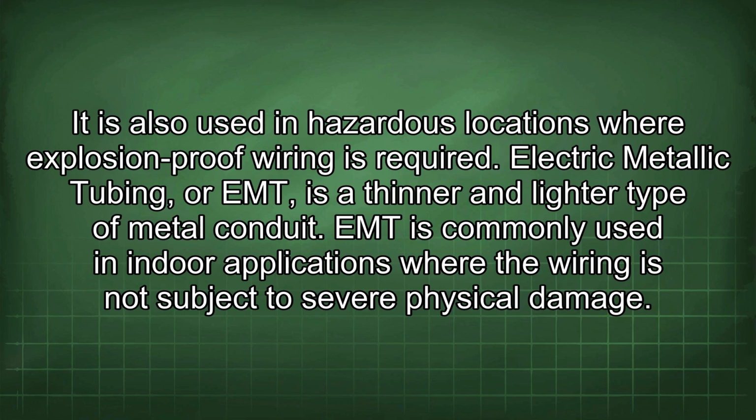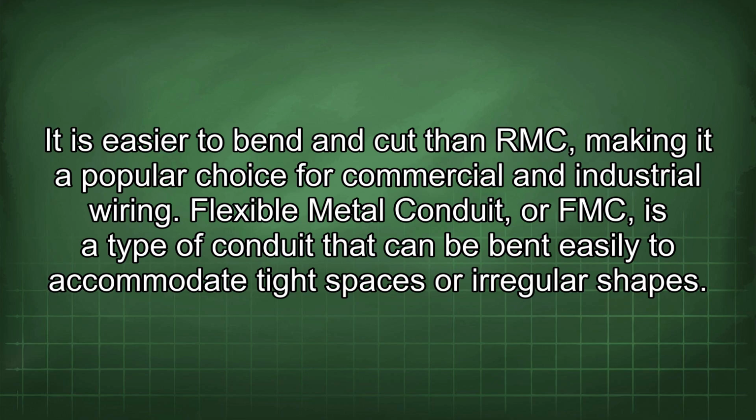Electric metallic tubing, or EMT, is a thinner and lighter type of metal conduit. EMT is commonly used in indoor applications where the wiring is not subject to severe physical damage. It is easier to bend and cut than RMC, making it a popular choice for commercial and industrial wiring.